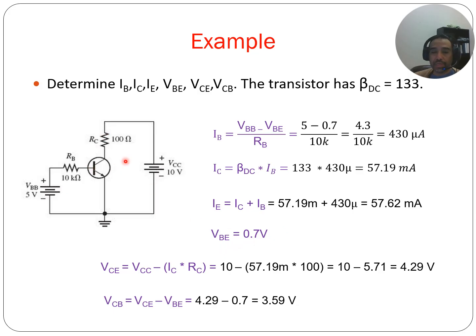And then VBE, because of the type of transistor and the material, it's silicon, a silicon diode. I keep saying silicon. That's already set by manufacturing, so it's set to be around 0.7 volts. Now, you've learned with your diode labs that it isn't actually exactly 0.7. It could be like 0.69 something. For calculations, just use 0.7 to simplify it, and that's another place where you might have some inherent error in your calculations.